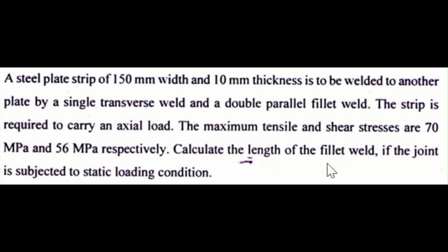Here, length of fillet weld means we have to find the length of the parallel fillet weld. The 150 will obviously be the length of the transverse weld. When they have not mentioned it, you have to know that the length of the fillet weld means we have to determine the parallel fillet weld. And the joint is subject to static loading condition. Okay, let's look at the solution.